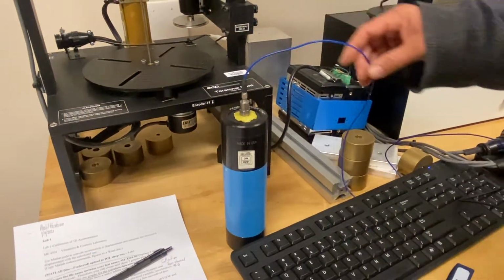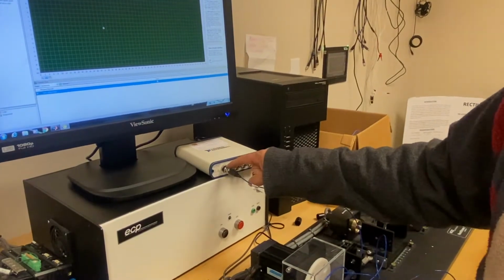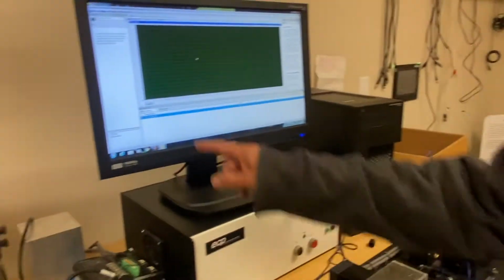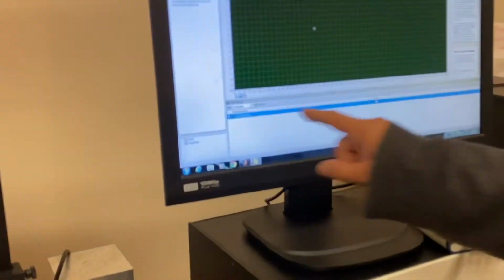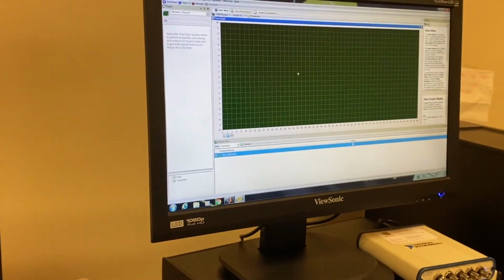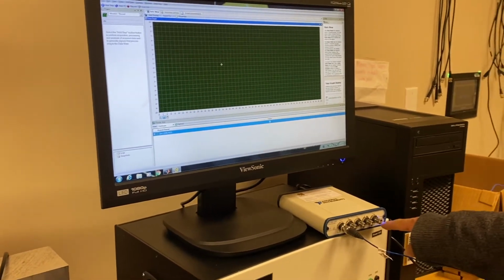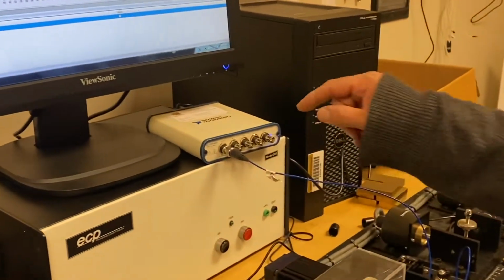Can you show this sensor? This sensor has been wired into this AI0, which is analog input 0, and we want to locate it. This should appear over here. If there is no device here, it means you have to apply some power. This should turn on, the light should turn on, the blue light.